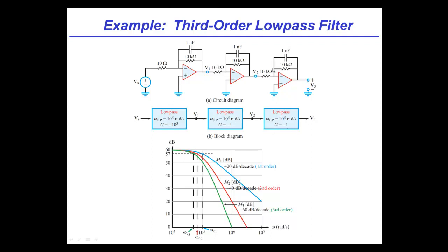And remember, this is the beauty of these systems. If you tried to do this passively, each of these would cut off more of the signal. Whereas here we can have a really high gain to begin with, and then if there's any attenuation in the others, we still end up with a net pretty good filter. Or backwards, right? Vivek, you're kind of an expert on this. I could have the front end one have a crappy gain but a very good input impedance, and then you can arrange them as you need to.